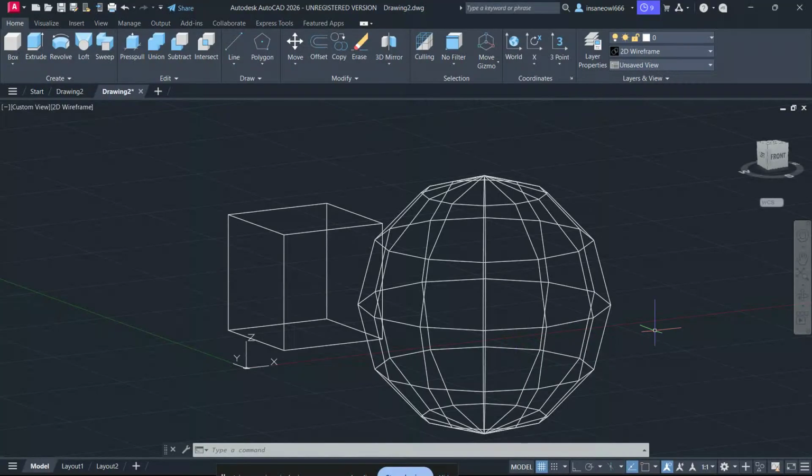If you're seeing AutoCAD error code 97008, you're dealing with a Boolean modeling problem, and in this video I'll show you exactly what it means and how to fix it step by step. This error usually happens when AutoCAD's ShapeManager engine can't resolve a union, subtract, or intersect operation. In simple terms, it runs into a face-edge intersection problem, which means one solid is cutting across another in a way the software can't calculate cleanly. The good news is that this is usually fixable without starting your drawing over.